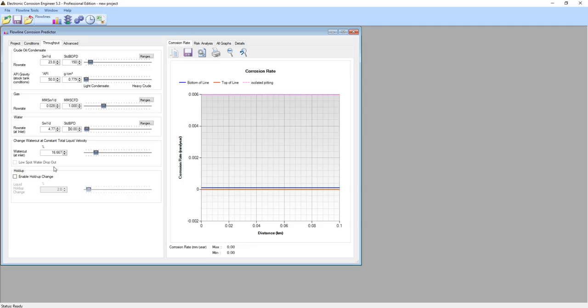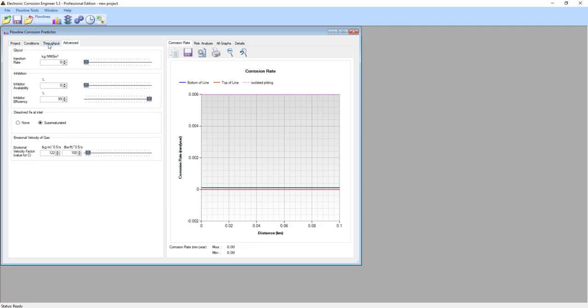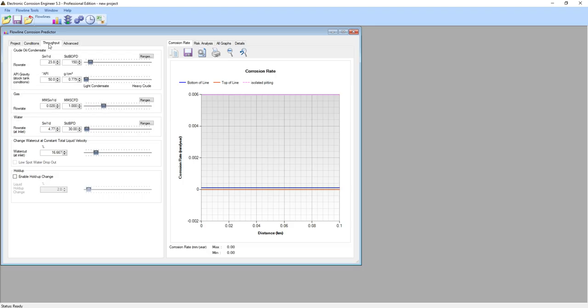All the cells in the advanced tab will remain empty as we are not using corrosion inhibitor or glycol in our vessel. I prefer to have all the other cells empty. I don't want to make it difficult at this stage. We will have another comprehensive tutorial about ACE, and there I will explain the rest of the boxes in the software.